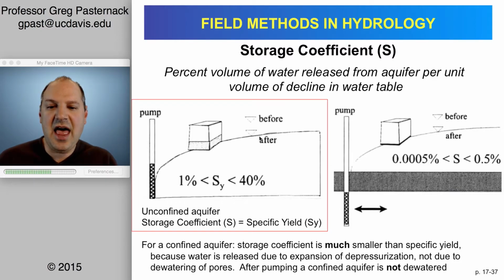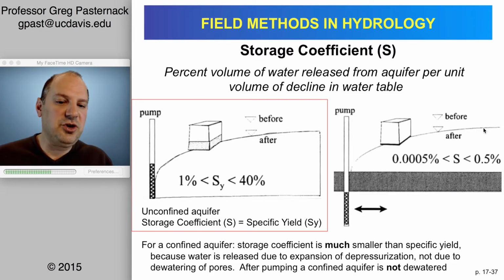In the case on the left, water is literally flowing down to the well, laterally and vertically. In the case on the right, the water is flowing horizontally from within the confined aquifer to the screened interval of the pump. The water surface, or the hydraulic head gradient, is there and that's sloped, but the water itself is not.